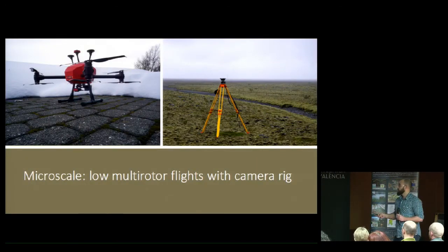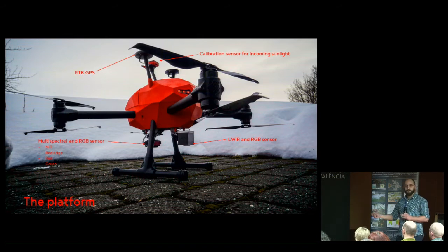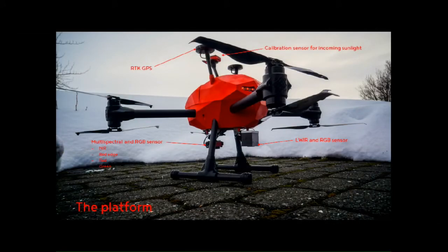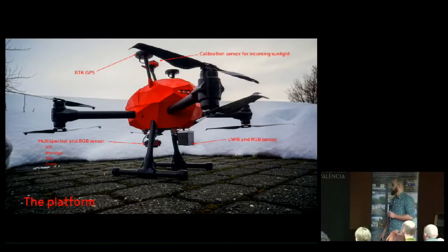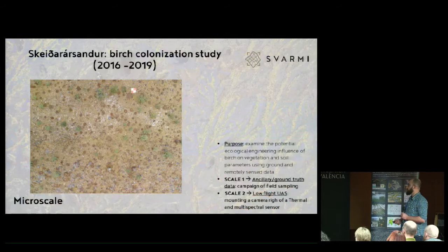What we will be using is our own in-house created drone. We also create our own drones, so we will be continuously mapping this area with this type of drone that has 2 RTK GPS and an integrated Sequoia and a thermal radiometric camera. We also have an octocopter, which can last about 30 minutes of flight according to our current estimations. We'll be using these continuously through the summer to create high resolution spatial datasets, but also high temporal datasets. This is one of the ideas to look at the microscale.